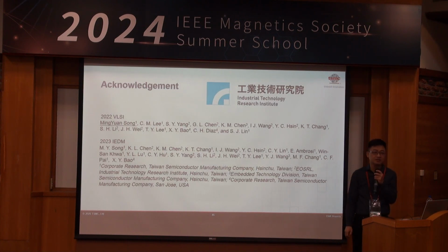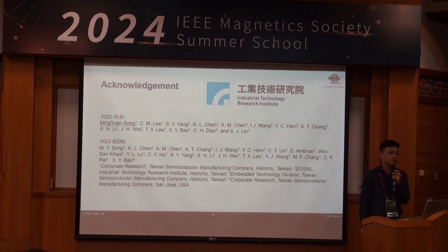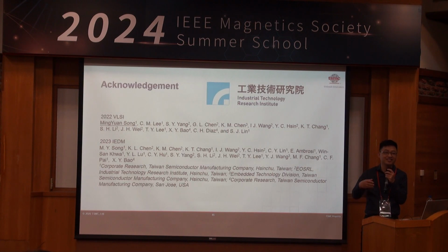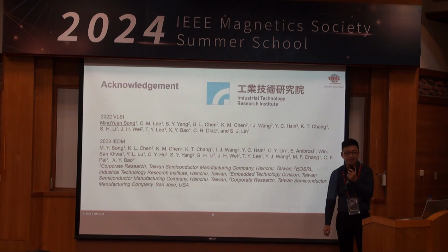And what is the magnet that TSMC used? Above the doped tungsten is cobalt iron boron. And the free layer structure is kind of tricky. It's not a single layer. You need some engineering, so that could also be part of the reason for the high spin-Hall angle.